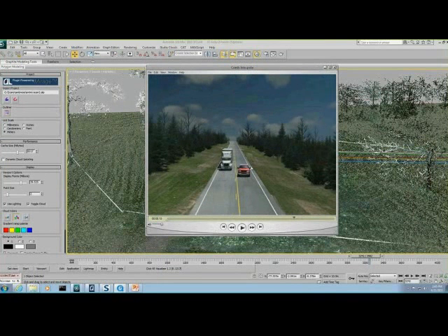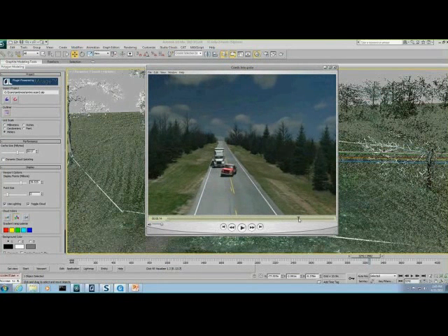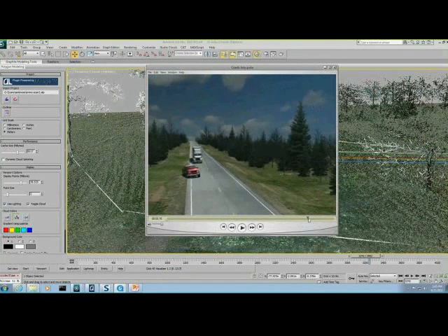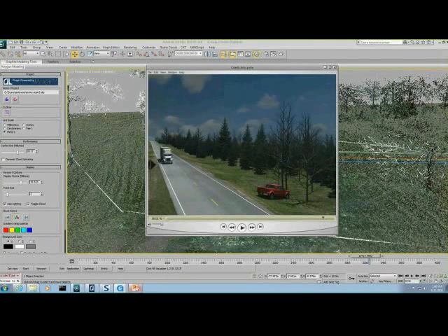And in this, there was a long decline, a long hill. And so the survey points that we had were probably 300 or 400 feet apart. So that means all of these extra details, the ditch lines, everything, we have to do from a photograph if there's not a data point there.